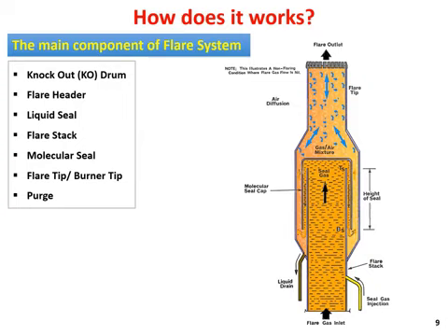So what we have in our flaring system is the flare gas, which is, let's say, hydrocarbon coming from any process equipment, collected in a knockout drum. Then it goes to the flare system. Here, most of the time, we need to mix it with some gas. Let's say it can be air or steam, to increase the pressure and make sure this gas is going out of the flare properly. Or we need some combustion agent, like air that has oxygen. So this goes through this gas seal, this part.